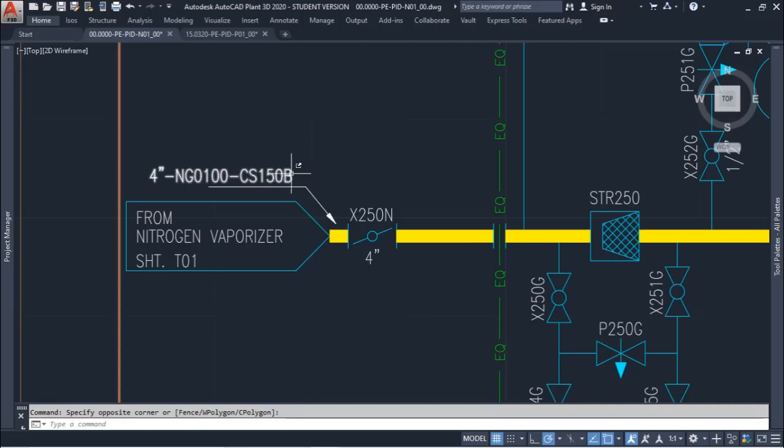And B is a kind of material related to carbon steel. Once you get familiar with P&IDs, you start understanding the line numbering for any kind of P&ID, but the correct way to know what represents each information in line numbering is consulting the instrumentation legend and symbols of your project.